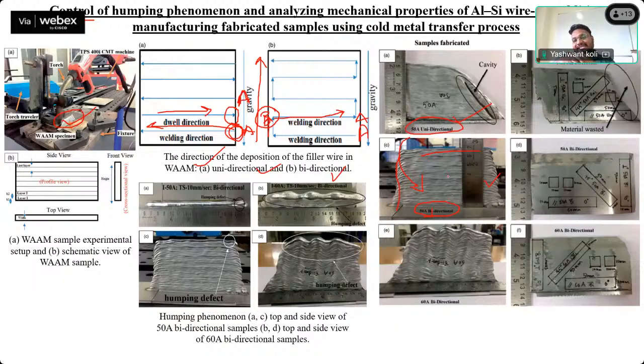It is almost 98-99% of the commercially available aluminium density, comparable with that. So we can check the density by Archimedes principle. We can cut the sample and dip it in the water, and we can weigh that. So using the Archimedes principle, we can check the density. The bulk density can be formulated, and we can compare with the commercially available aluminum alloys.